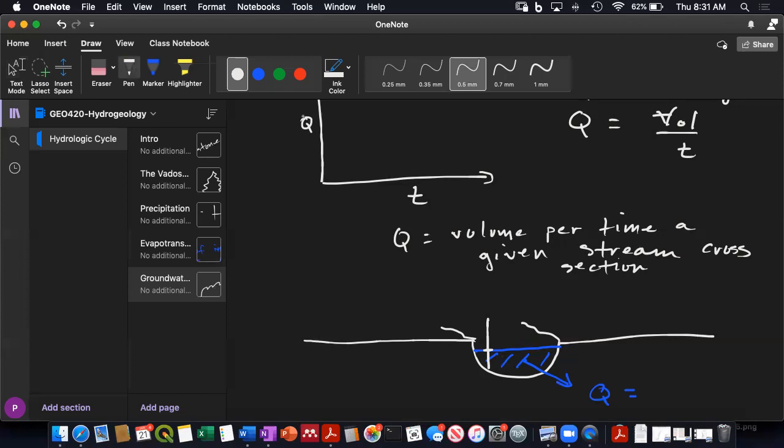Yeah, so when you go out and gauge a stream, you go out with an instrument and take measurements at a bunch of points in the stream and a bunch of depths. You take the velocity with a flow meter, and you figure out the velocity of the fluid movement here. So the first thing we do, that Bailey mentioned, was velocity.